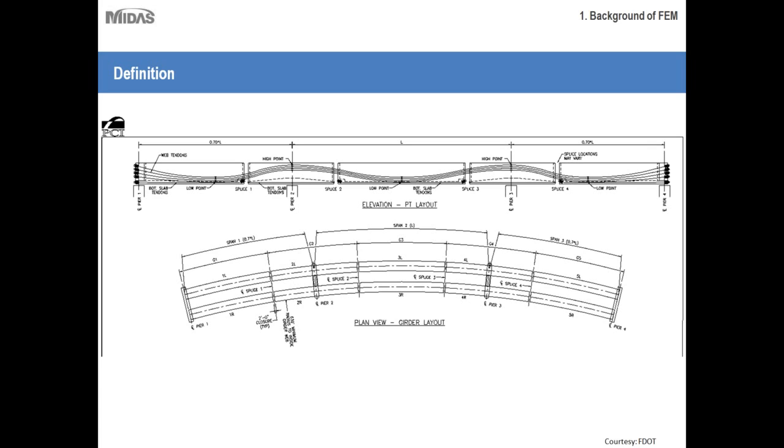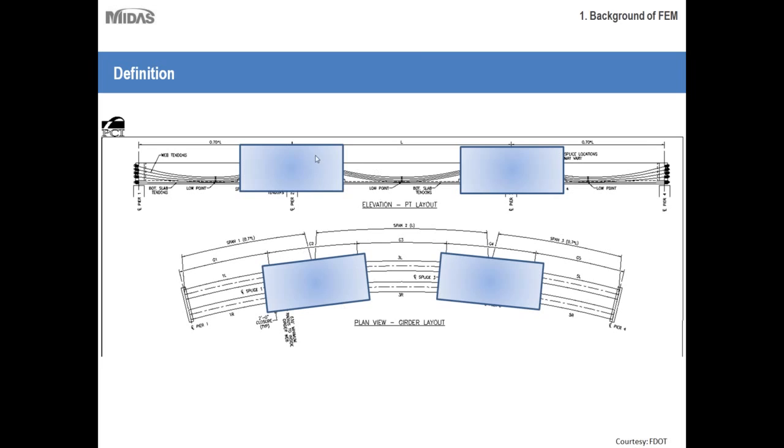This is somewhat in line with accelerated bridge construction practices, where you can cast these segments along the curvature, lift them up, and put them here in the zone where it is supported over the piers. In these zones you have to apply the lid slab on top to cover the U-girder opening and provide enough stiffness to the section to avoid any kind of torsion in the segment and give it its stability. Because after this stage we will be doing the post tensioning and applying the deck slab on top of it.